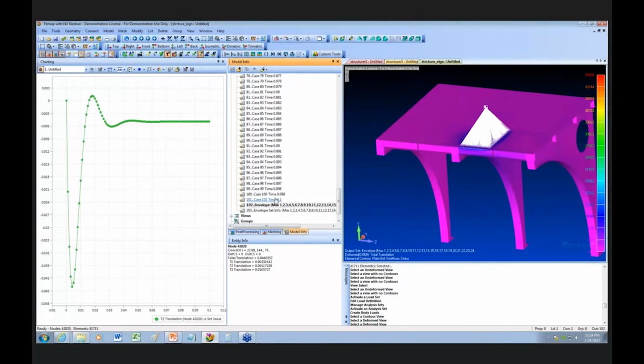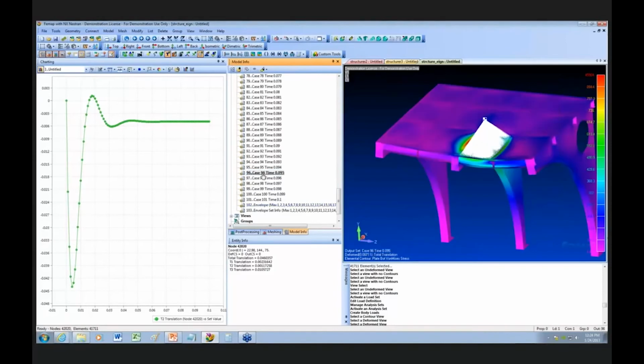And I can come back here, and I want to come over here. I want to see where, when all the energy has been damped out, you can see this damping that's taking place right here. At some point, all this kinetic energy has been damped out, and it goes to a static solution. And so I want to come over and look at what's happening statically here.